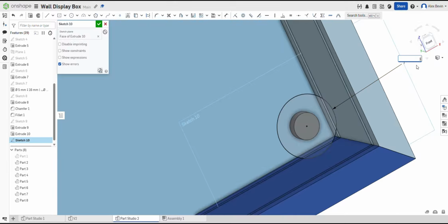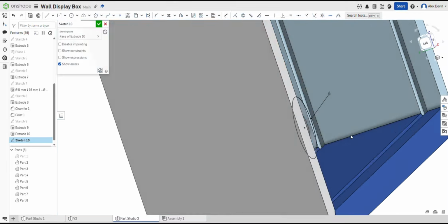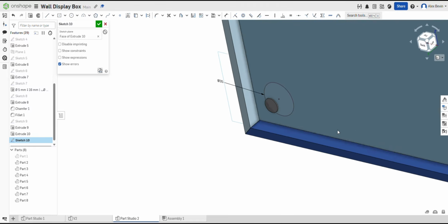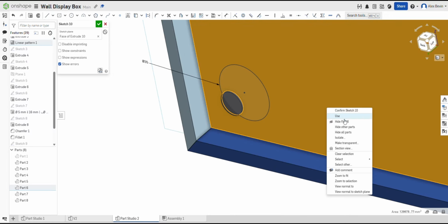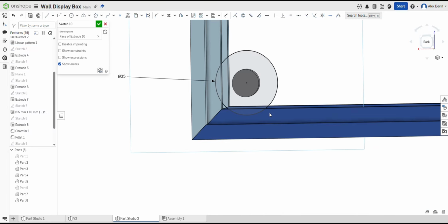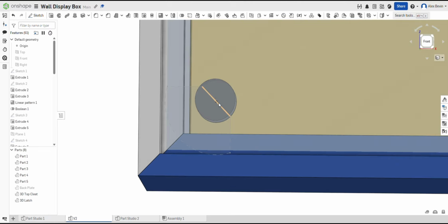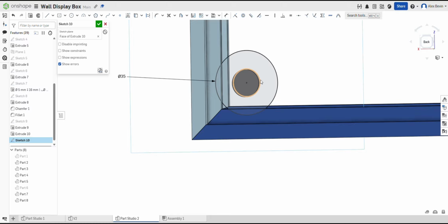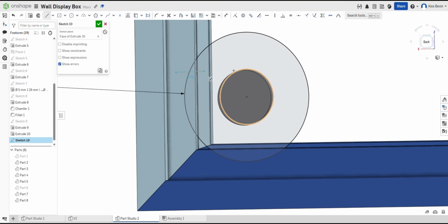Step 4. Start sketching the latch profile. Reference geometry. Now I'm going to hide the acrylic so we can see clearly, and I'll sketch on the circular face. This is where the latch geometry starts. Quick note. In the exemplar, you'll see an 18mm circle. That's not the acrylic hole. That's the diameter of the inner yellow cap on the printed part. You'll also see U30. That's just a reference circle to help shape the latch.